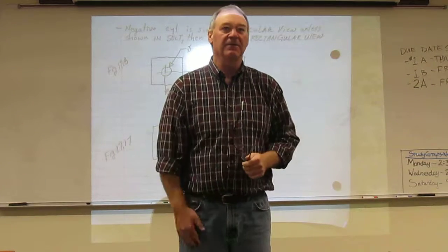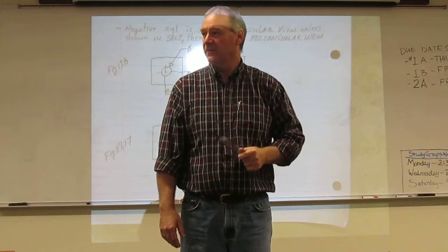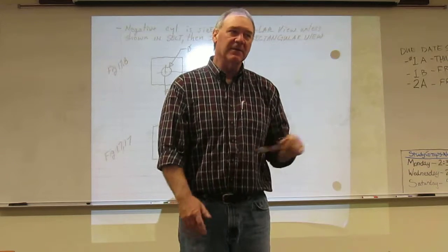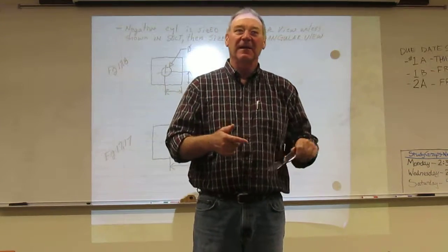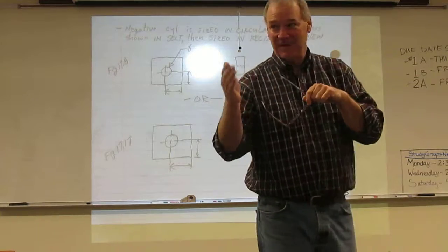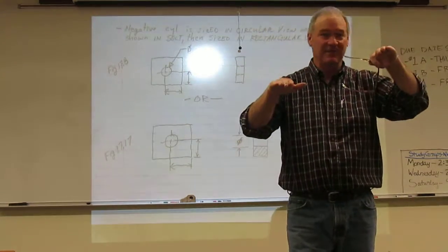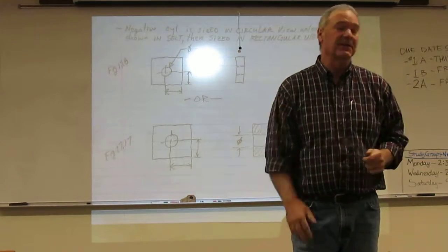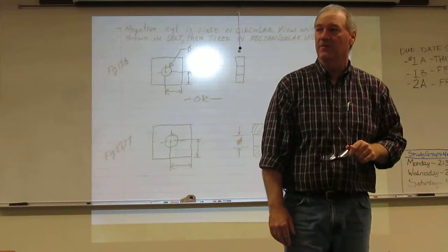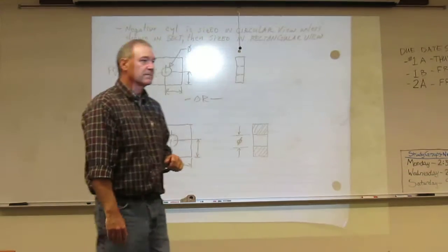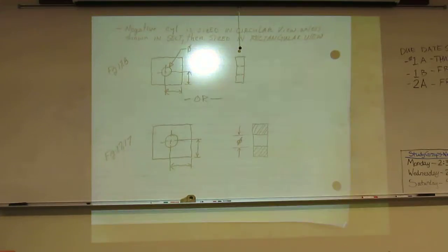No, they come in tangent. So they self-locate. So that's the only caveat. You've got to watch for the ones where you don't need dimensional information to build it, it's off linear and tangencies, then you don't have to locate it. It's a self-locating curve. And we'll look at examples of that too.